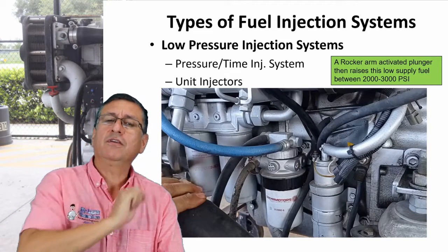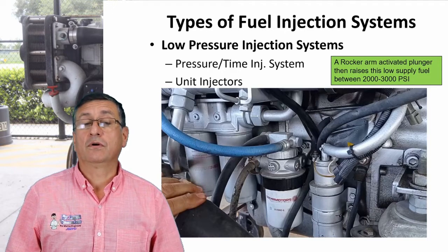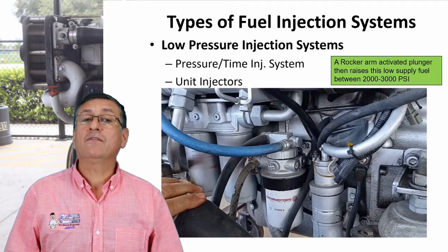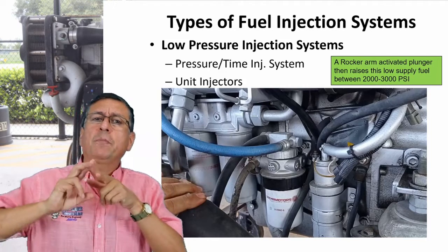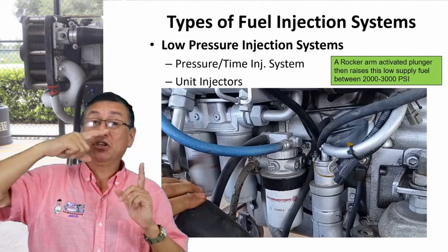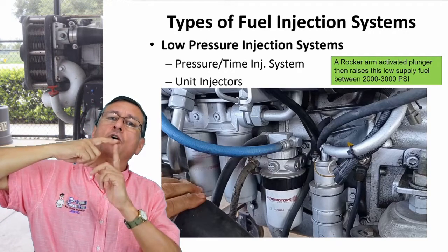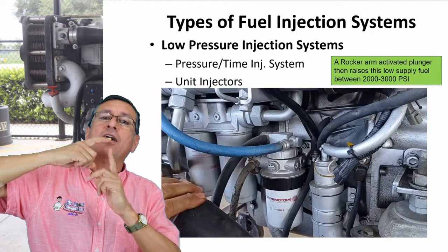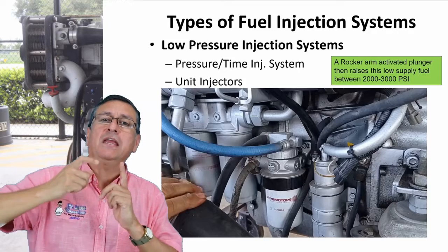Right now in this video I am going to show you two types of injectors. In one of them, this is a new engine, the injector opens because the loads of the camshaft compress the injector and compress the spring, and the fuel enters.